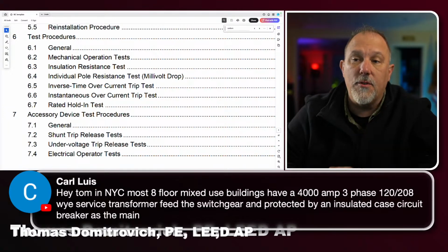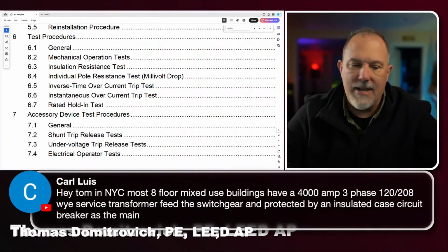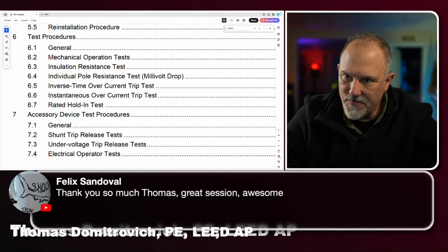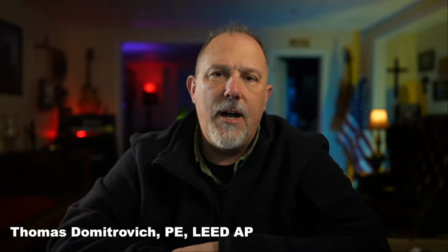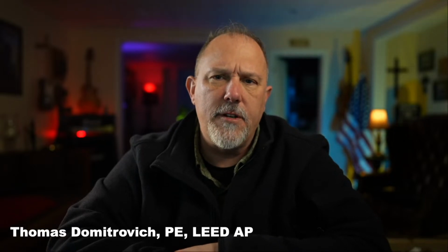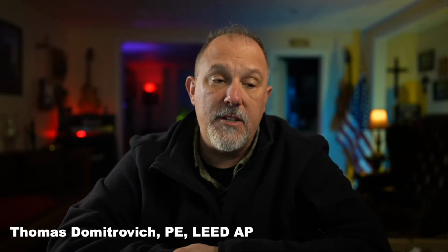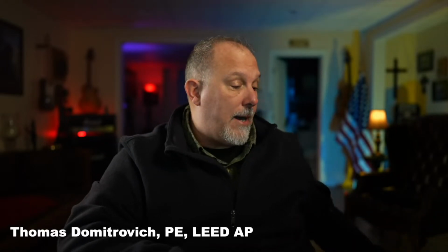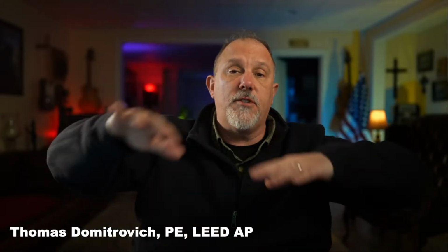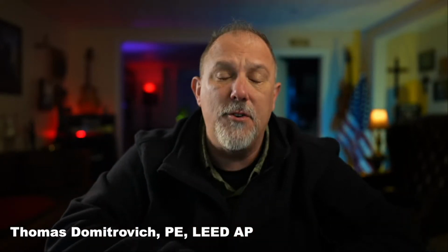And I'll bet you, New York City, I remember one time I asked the chief electrical inspector, I'm not going to throw names, I said, what's the maximum available fault current that you have in downtown New York? And he said 200,000 amps. He says, do you want to know why? I says, well, yeah, I know why. Because you have parallel transformers, a secondary network. He goes, no, because you don't make anything bigger.